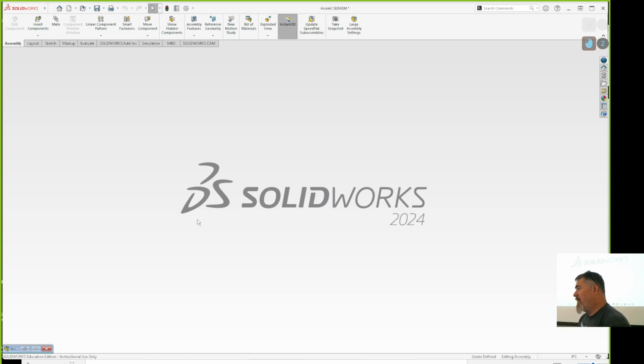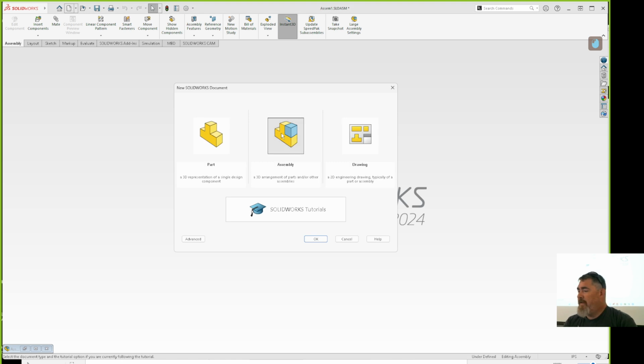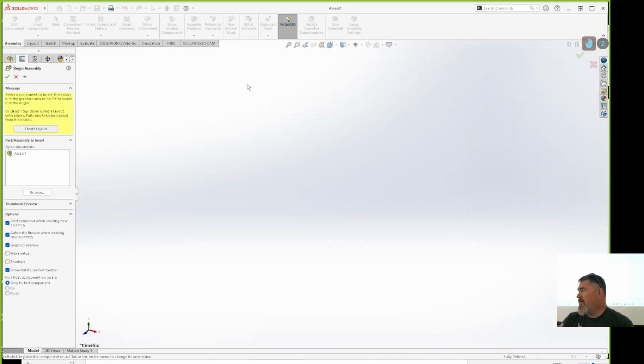The next thing we're going to work on is making an assembly in SolidWorks. And so I'm going to have you make some parts, just like usual. I have a tab that has a bunch of parts for you to make. And so we're going to go into new and pick an assembly. So just double click on it or click assembly and click OK, it doesn't matter.